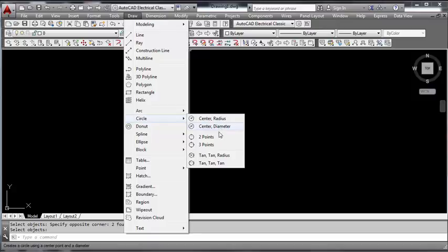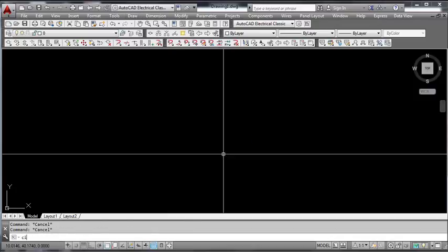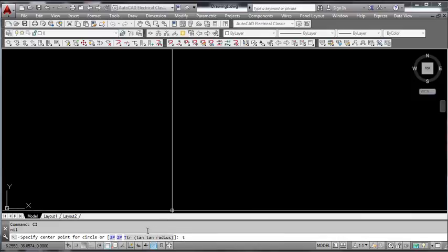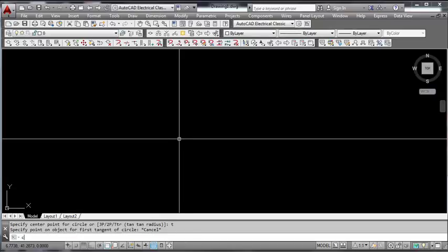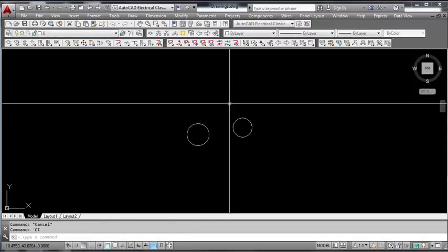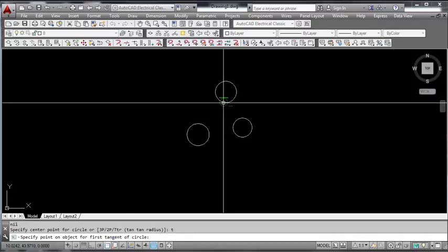I have seen many people keep this on at all times, but that is not recommended. That is not at all recommended. That is not good. Sometimes it catches the wrong points. You will not notice this, especially in big drawings, huge drawings. You cannot zoom in and check whether these lines are connected together or not. That will create some problems. So clear. I normally use what I need. I never choose this select all function.